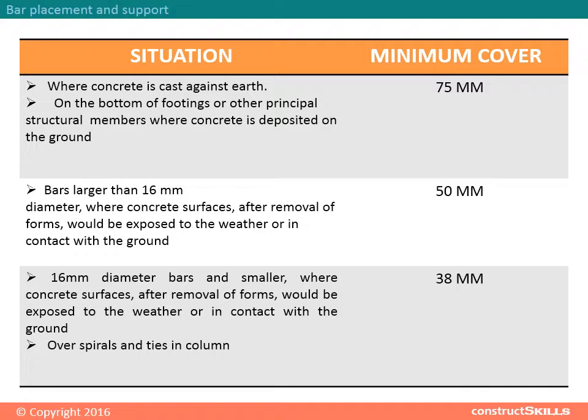Minimum cover provided according to situation. Where concrete is cast against earth, on the bottom of footings or other principal structural members where concrete is deposited on the ground, provide 75 mm cover.